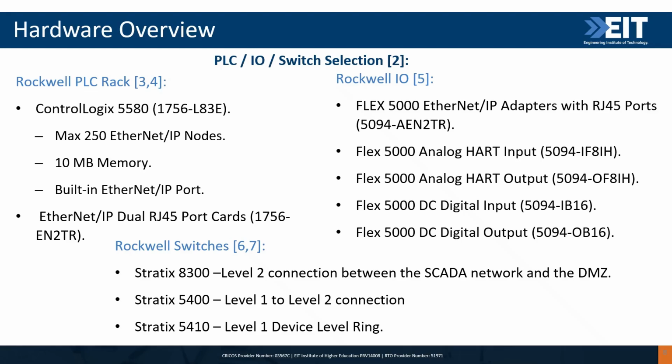DHCP will be enabled on the device level ring of the field equipment, and static IP address is assigned to each port. This minimizes the amount of field setup required for VFDs, soft starters, and electronic overload relays, and reduces the chance for error in initial startup.